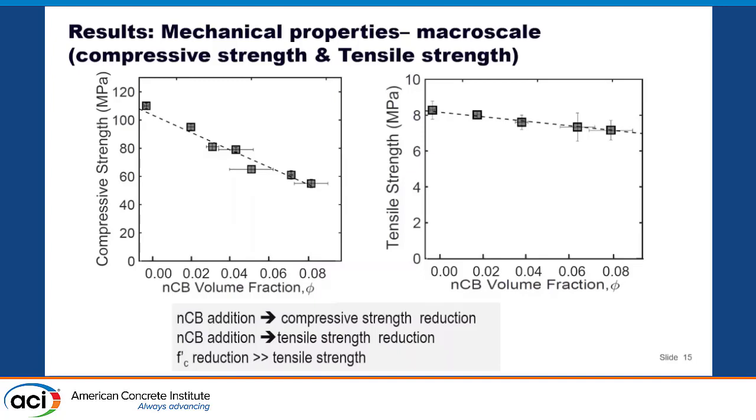Yeah, but this is 117, so plus or minus. Of course, we are getting more than 120 megapascals. You have not even reached the minimum strength of 120 megapascals to classify as UHPC, whereas the composition may be okay. Why have you got such a low compressive strength for a UHPC? Yeah, 117 is low, definitely, because 120 is the minimum. But why have you not achieved greater than 120? Because we are getting 160, 170 megapascals.